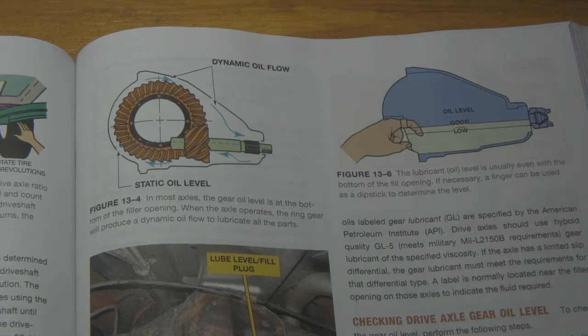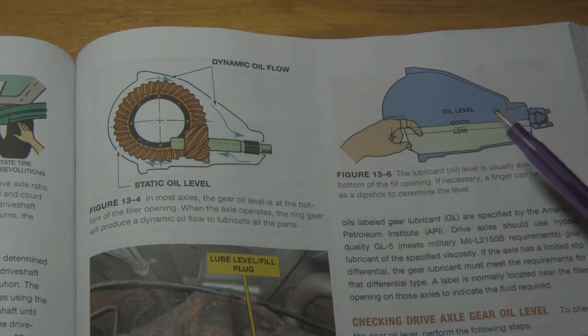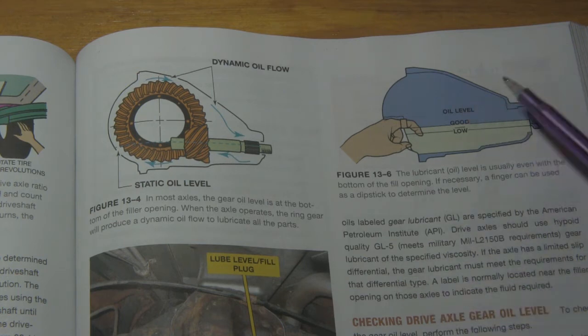They simply just require adequate, good oil that's not dirty, and they require adequate volume of oil. So you have to have the proper amount. And one of the ways we check for the proper amount is by simply taking the fill plug out of the top side of the differential and reaching our finger down inside there. And most manufacturers have a spec that says somewhere around a half inch below the fill line is where you should have the fluid level be.